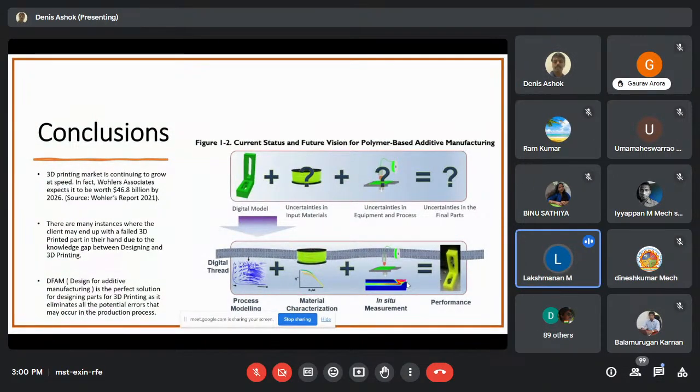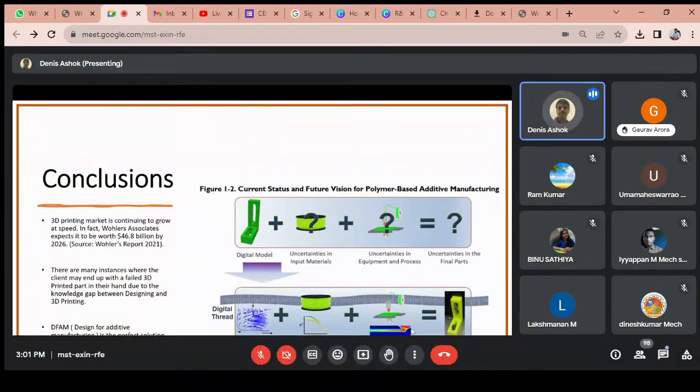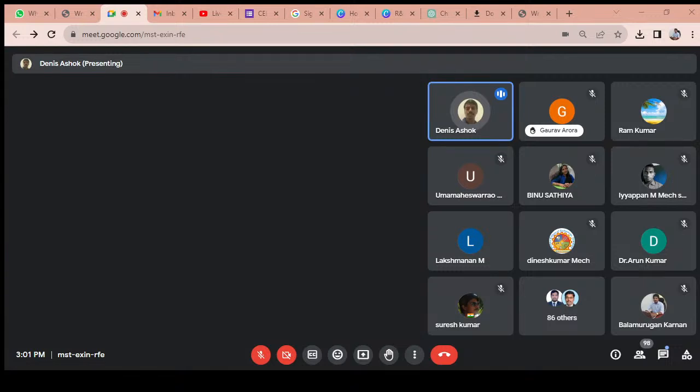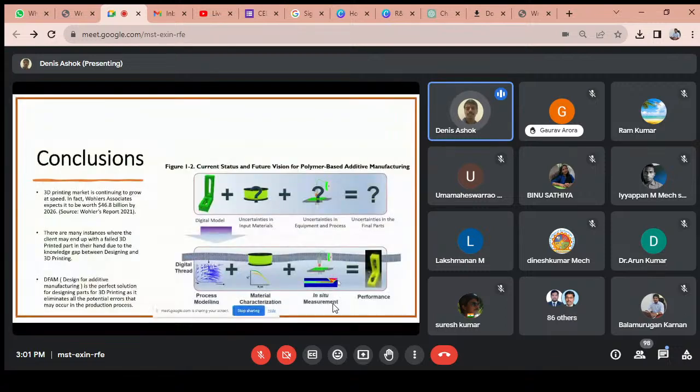Can we do some texture-oriented fabrication in metal additive, sir? Yes, sir. We can engineer the texture as well, because we have all the flexibility of our design, and the manufacturing can be controlled to meet our texture. By confirming through EBSD analysis, we can confirm what type of texture is generated during fabrication. Yes, sir, that can be done.